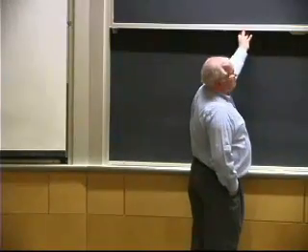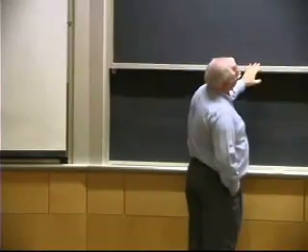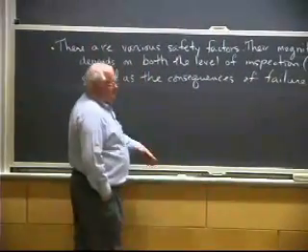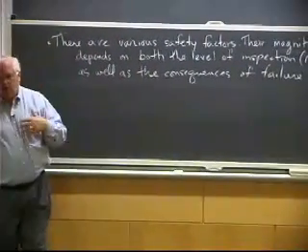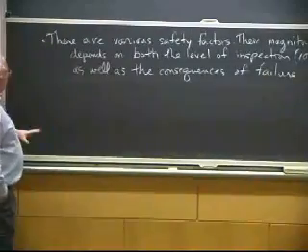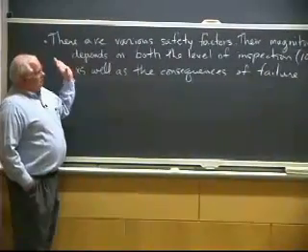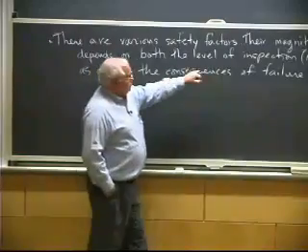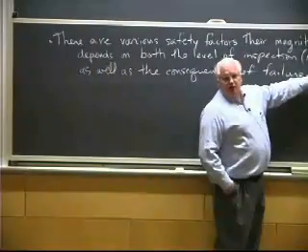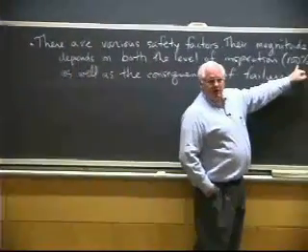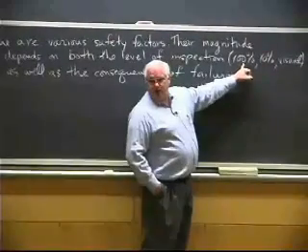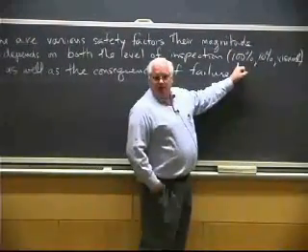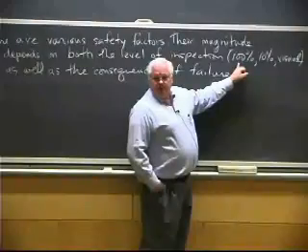The level of inspection and the safety factor that's used in the design, or the proof testing, or the design verification, or whatever. There are lots of different safety factors, but the safety factor that's used depends on the level of inspection. If I do 100% inspection and I know there's not any flaws bigger than an eighth of an inch, or I have reasonable probability of knowing that, then I can tolerate a smaller safety factor.